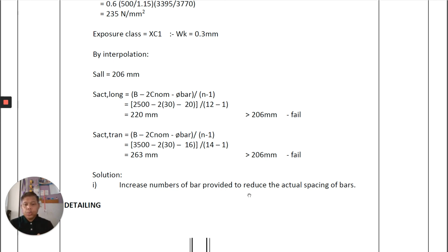What we have to do, this is back to the things that I already shared with you before, where we have to provide the largest number of reinforcement bars, because it will affect the value here. So that's why we can have at least 15 or 20, so that we make sure that the actual spacing here is less than the allowable here. So this is the way we provide the number of reinforcement bars in order to control the crack check of the foundation.